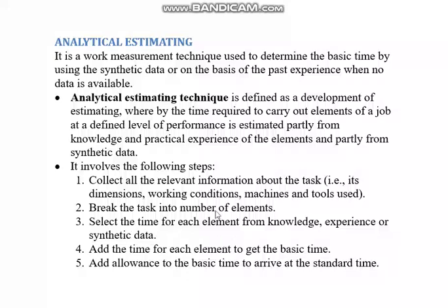See, till now what we have done. We have taken a task and gathered all the information that we can about the task. Second, we have broken that task into many pieces. And the third thing is, for each element, either from our experience or from the synthetic data, we have selected the time that is required to complete that element.